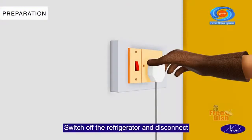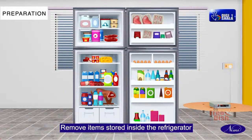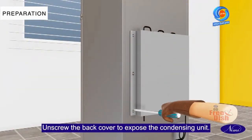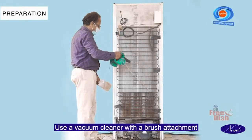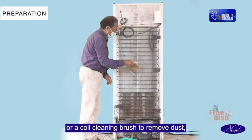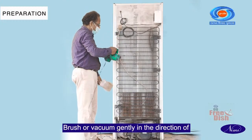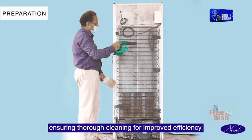Switch off the refrigerator and disconnect the plug from the socket. Remove items stored inside the refrigerator and gently pull the unit forward. Unscrew the back cover to expose the condensing unit. Use a vacuum cleaner with a brush attachment or a coil cleaning brush to remove dust, dirt, and debris from the condenser coils.